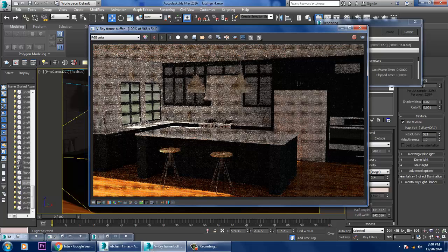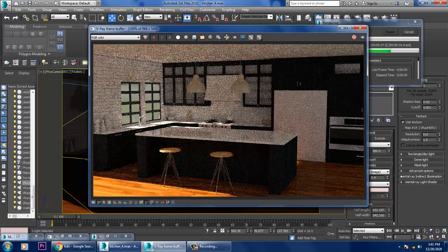The light also will emit light accordingly, since we have assigned a HDRI texture. The bounce of the HDRI will work on any of the reflective surfaces inside this environment. That's how you set your HDRI maps.